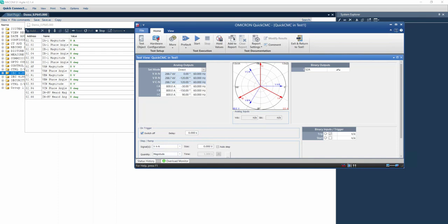And we have introduced the concepts of process bus and station bus. The other part is the GOOSE messages, which stands for Generic Object Oriented Substation Event. And we have said that it's peer-to-peer communication in protection and control applications.